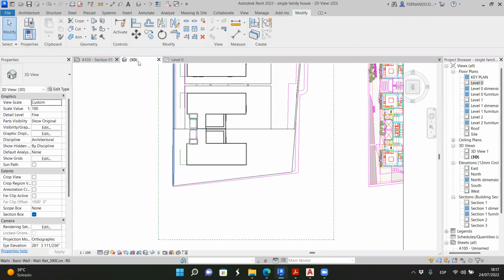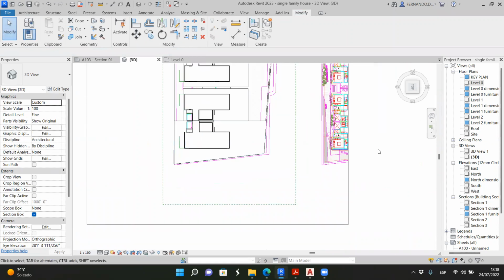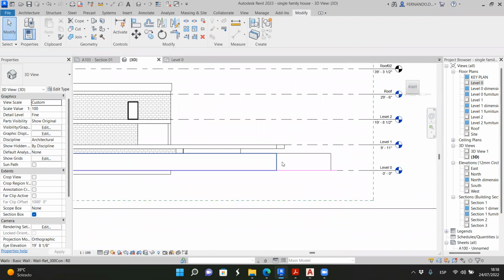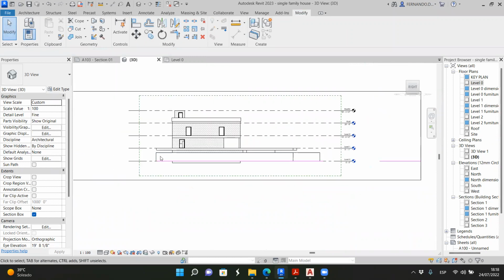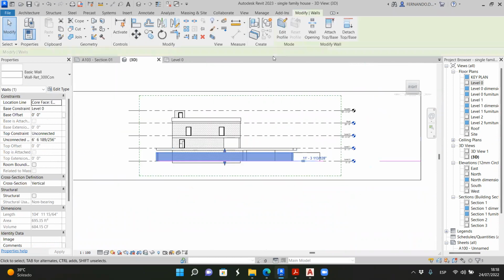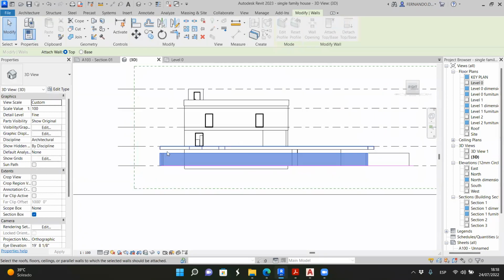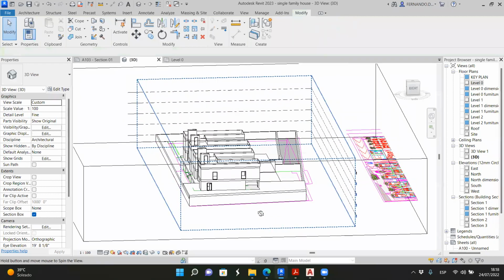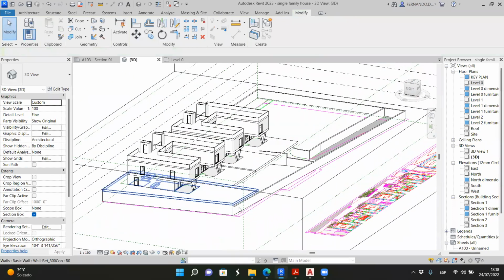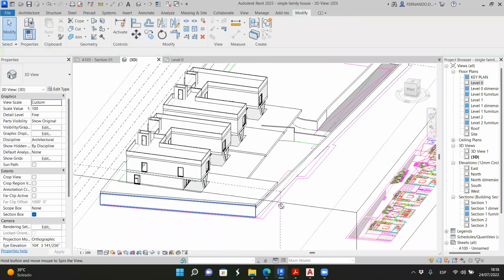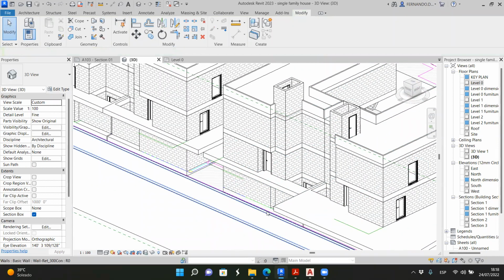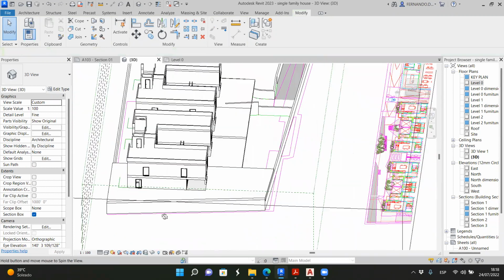Okay, and probably now it will be attached. No, but we can do it. If we select this and we select attach to top base and we select this one, we can do it. Okay, so we have to extend all these floors to the retaining wall, and then we can attach everything to that.